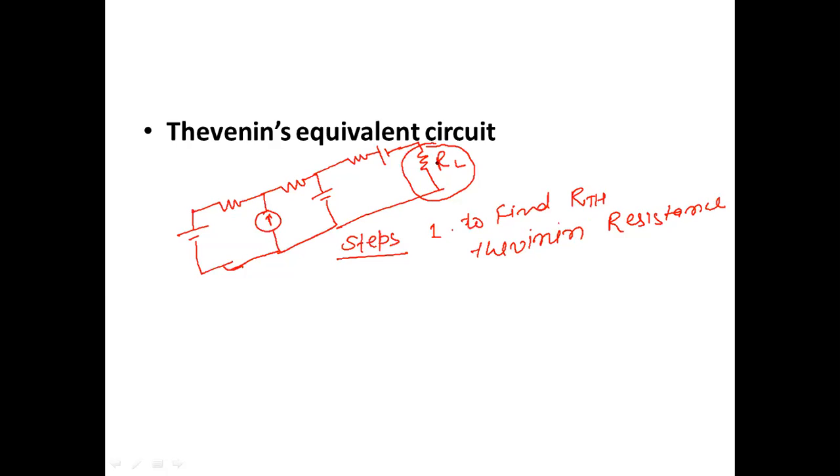All independent voltage sources are short circuited and all independent current sources are open circuited.